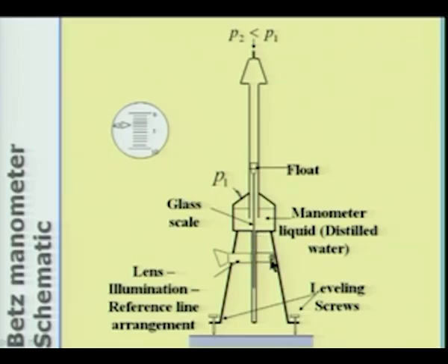And what I will do is use a lamp and two lenses here, and using the eye I can focus on the scale. I can put a spot on the scale, and there is a vernier which will indicate the value of the height. Here I have simply shown 42 point something, so many millimeters of water column.